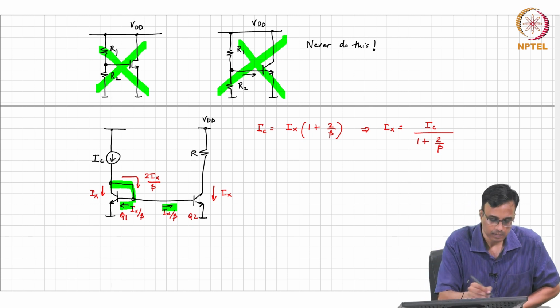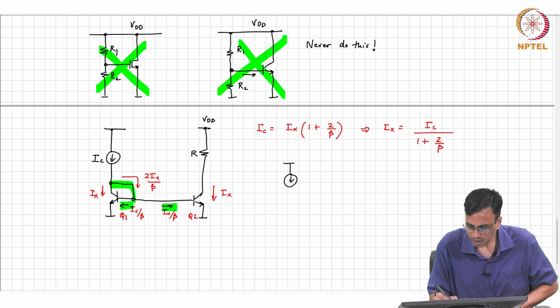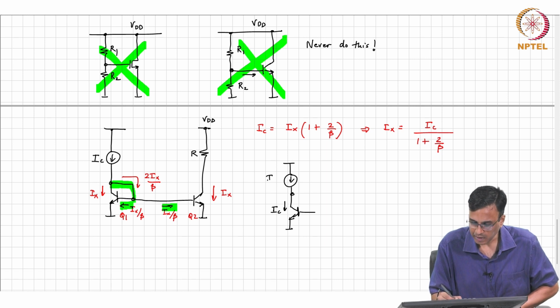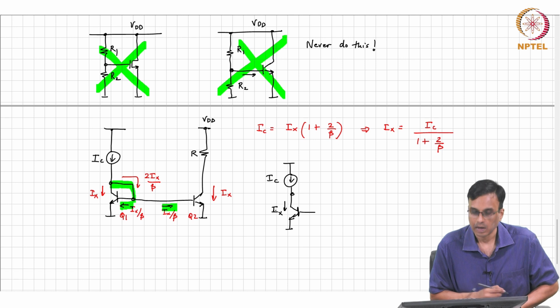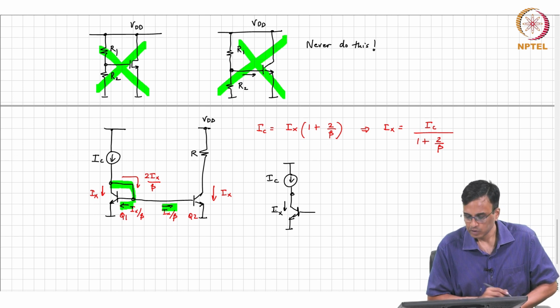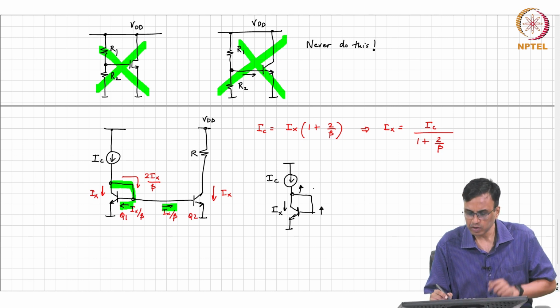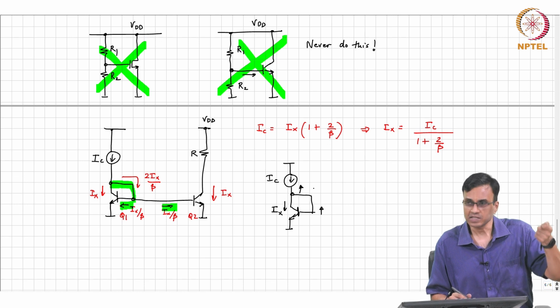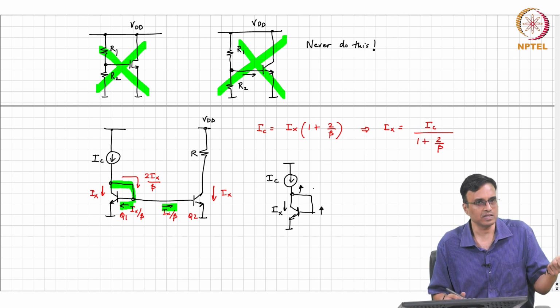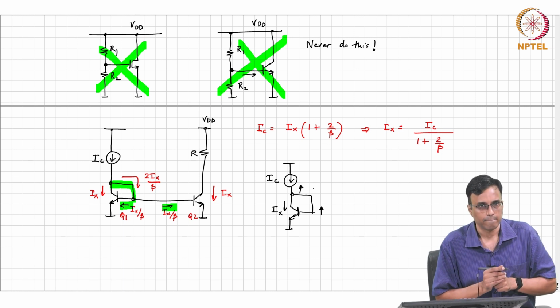How did we get the current mirror? We compare the collector current with the reference current, and go and kick the base voltage in the right direction, correct. So, basically if this goes up, this voltage must go up. The easiest thing to do in the MOS case was simply short these two, and we want the voltage of the base to be the same as that of the collector, right. In the MOS case, that was very easy. We just created a short circuit, and because the gate did not draw any current, we were okay, all right.